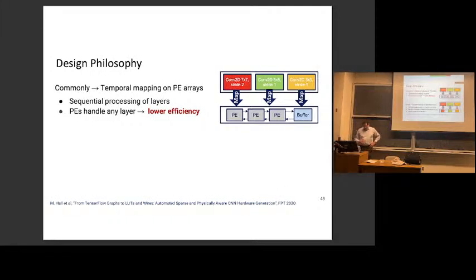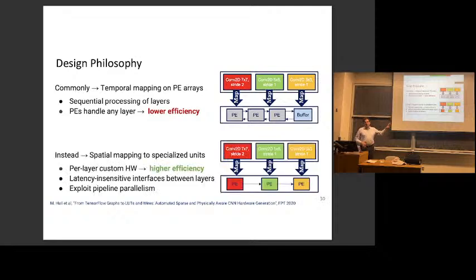So the architecture I'm about to show you, HPipe, doesn't do that. It takes a different approach. Basically, it creates a different PE for every one of these layers. So you can see you've got 3 different colors of PEs here. Each of these layers maps to a specific PE that we've built inside of the FPGA. And those PEs just feed data to each other.